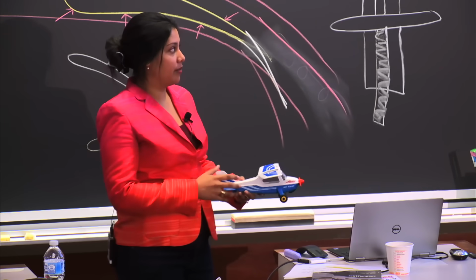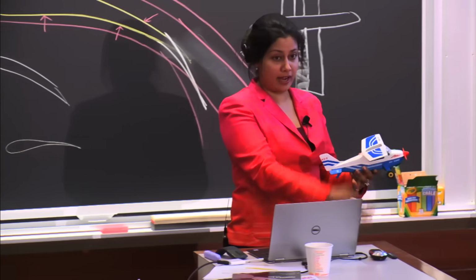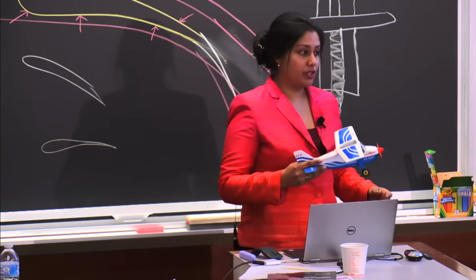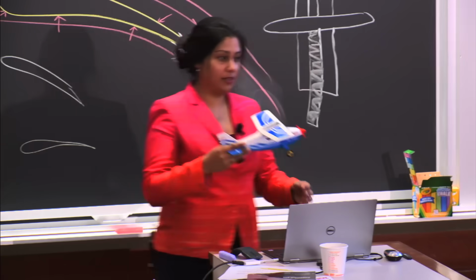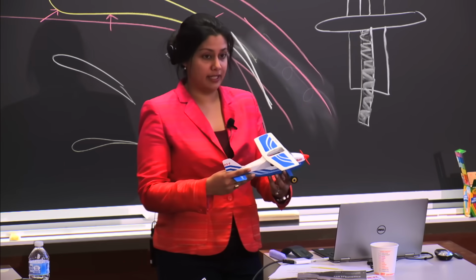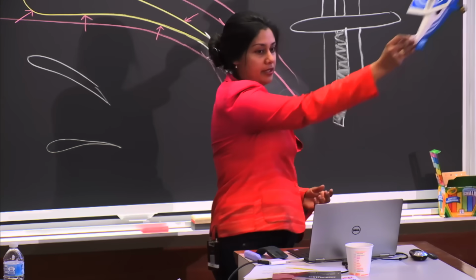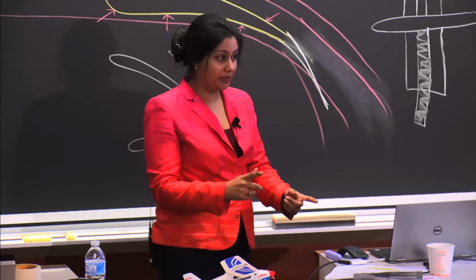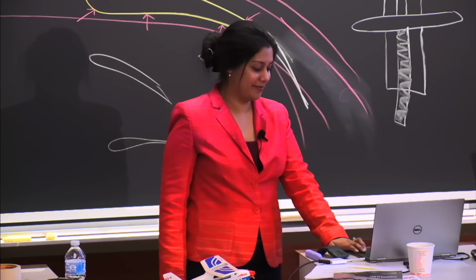And so this is why ground effect is really important, is that you can kind of float over the ground because you're so close to the ground that the ground is blocking some of the effects of the air. And so what you want to do is really make sure that you continue your ground roll, even if you're a little bit airborne, stay close to the ground until your airspeed comes up to that rotate speed, so in this case 55 knots, and then you pull back on your yoke to take off. So when does ground effect happen? When you're close to the ground, when you're within one wingspan of the ground.